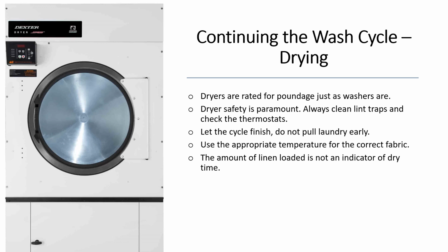As always, safety should be kept in mind. Lint traps need to be cleaned after every cycle. The thermostat should be working and gas flames should be checked for proper adjustment. Failure to care for the dryer can result in smell and scorched linens or malfunctions of the dryer.